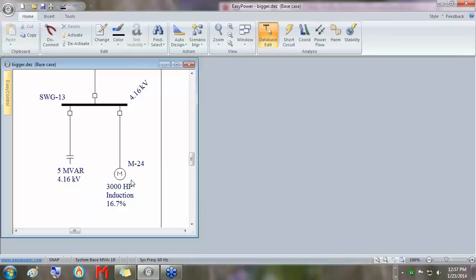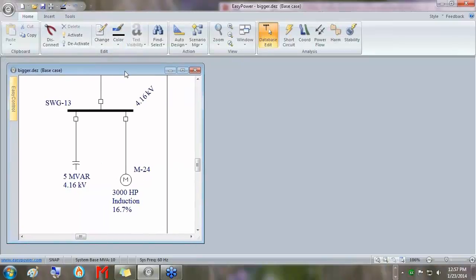So why don't we start first by going right into stability without actually putting in any data? I think you'd find that an interesting capability of the stability package. You don't need any data. It's just going to model Thevenin equivalence, and all your loads on your system are constant impedance. But it's amazing the number of different things you might be able to do later on. I hope to mention a few of those near the end of our presentation.